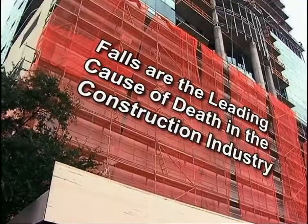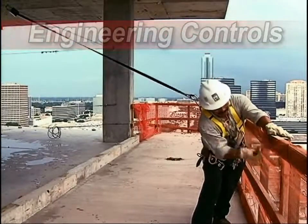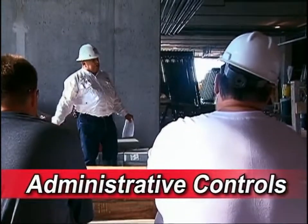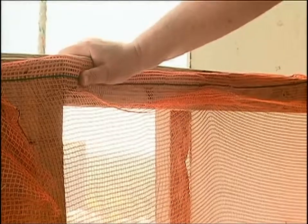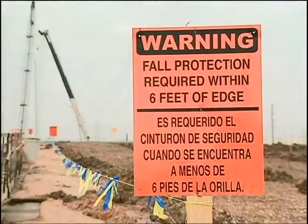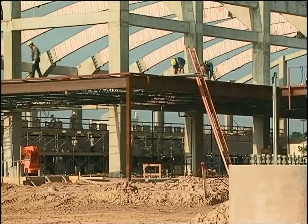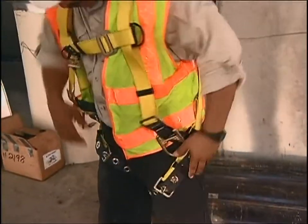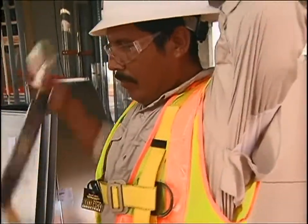In many cases, employers are able to use engineering controls, such as guardrail systems, and administrative controls, including training and safe work practices, to help minimize or eliminate fall hazards. However, when these controls do not provide an acceptable level of protection, then it's essential to wear a personal fall arrest system. Workers on construction sites who are exposed to vertical drops of 6 feet or more may be required by law to wear a personal fall arrest system. If worn correctly, a personal fall arrest system can save a worker's life. If worn incorrectly, it can cause additional harm to the worker, possibly causing grave injury.